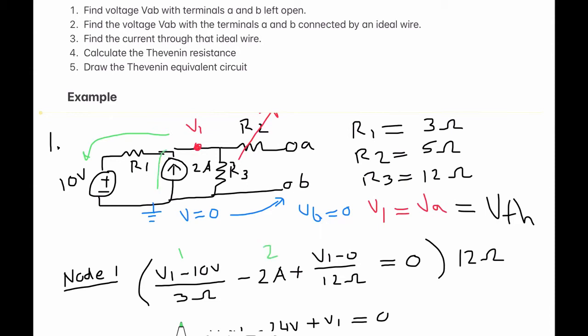And then the second branch, which will be here, is coming in, because I have this current source coming into it, into node V1, so therefore I'm assuming it's negative, because I'm using sign convention where any current coming into the node is negative, any current coming out of the node is positive, like this. And you can use the other sign convention too, so if you have your signs flipped, it should work out just the same, because you would just divide the whole thing by -1, and thus your sign convention would change. So it really doesn't matter, but that's the one I'm going to use.